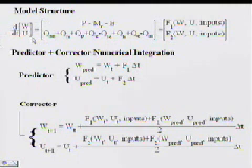Then we keep track of the energy contents. So the rate of change of energy content with time is all the energy fluxes: net radiation, incoming long wave, heat with precipitation, ground heat flux, outgoing long wave, sensible heat, latent heat, and melt outflux. And we can just write this in a general form, as these are functions of the state variables, W and U, as well as the model inputs.